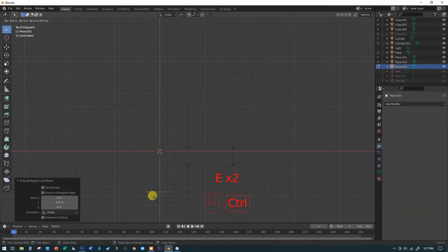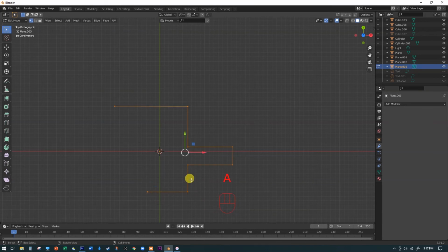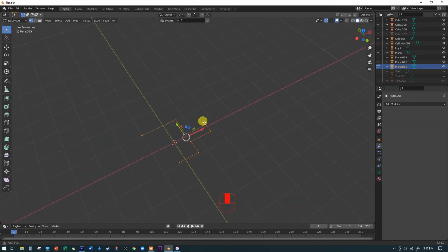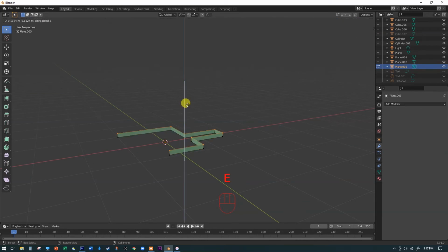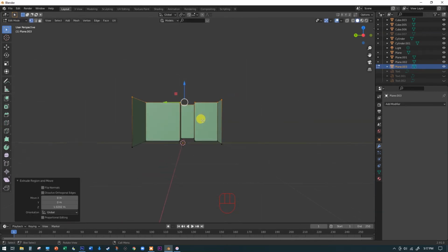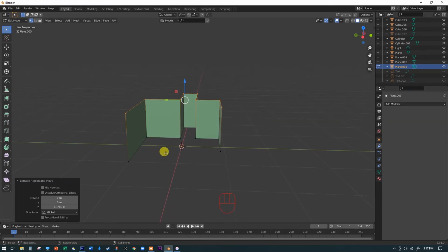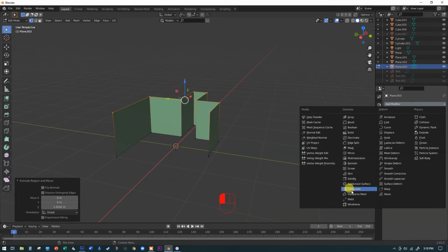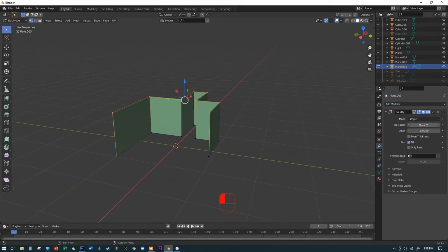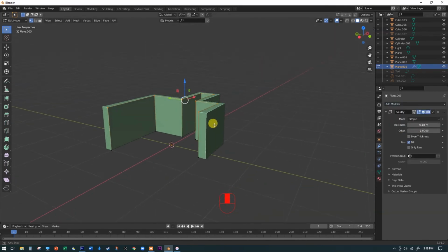And the nice thing about this version is that when you're all done, you've got all of these lines. I can just select all, and now if I move back into a perspective view, I can just hit the E key to extrude, and Z to lock it in the Z direction, and then I've just got my walls there. I don't have to do that trick about selecting the floor or the ceiling and making sure that you have it separated before you add the solidify modifier. You can just drop the solidify modifier right on here, and there are your walls.